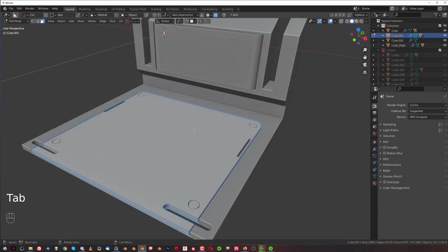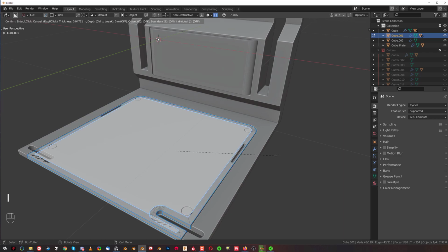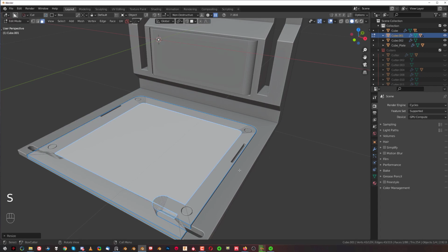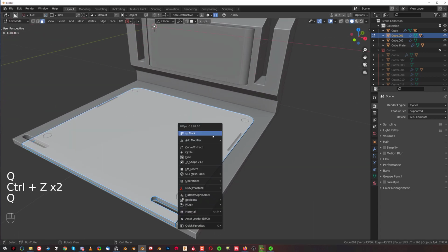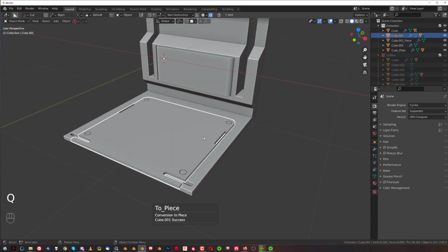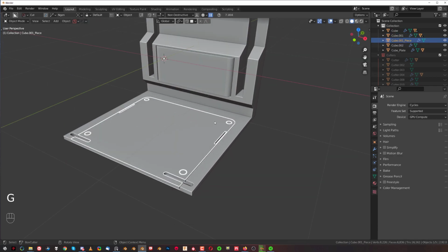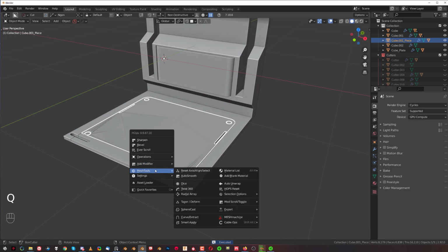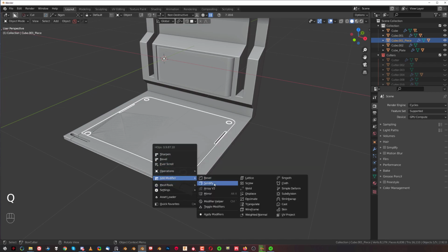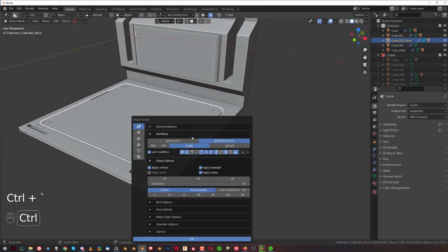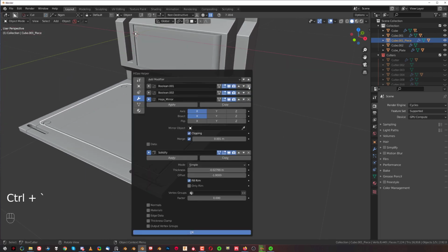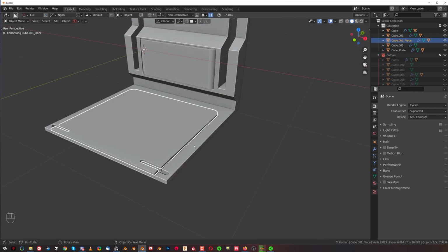Now let's grab this one here in the middle. This one is not sliced yet. The cutters are not applied, so we can inset it and then scale it a little bit in, okay, and then we can detach it. Or we can do it differently. We can simply control click on curve extrude, and now we got this plane on top, okay. Something like this. We can slice it here with an end gun like this, okay, and slice this top here, and let's solidify this. So let's add modifier, solidification, solidify it up a bit, and let's remove all the modifiers, right? So the boolean and mirror can stay, and it's cool.